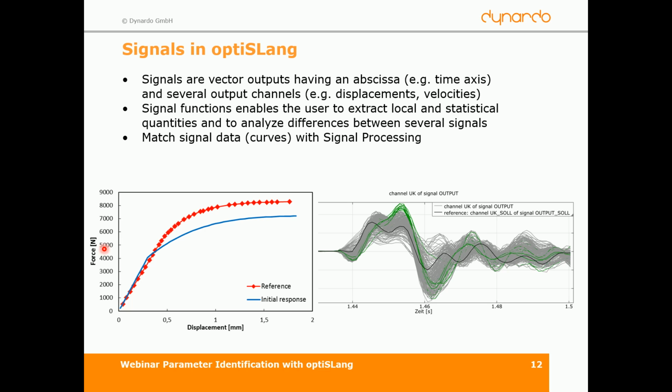And after having signals from simulation and measurement, we want to compare the simulation and reference curve. We can interpolate the points of simulation with respect to the points of measurements, and then we compare both of them, for example, using the sum of squared error.